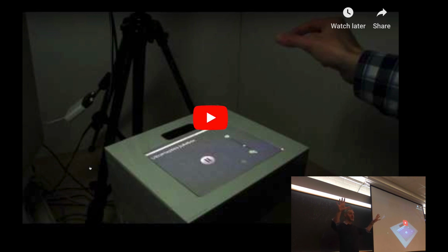So by setting the phase offsets carefully, you can create positive and negative interference at different points in three-dimensional space. The metaphor of the waves on the beach is still sort of in 2 dimensions, or 2.5 if you want. This is being done in 3 dimensions. So they mentioned putting these positive control points. They're setting the phase offset of these transducers so that they meet and produce more vibration at those green crosses. But they're also setting the phase offset in such a way that just around the point, they're also canceling out some of the vibration.